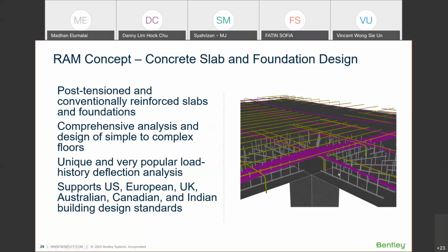So here you can see all this white color vertical reinforcement. These are shear studs, and there are manufacturers of shear studs in many countries. These are useful to withstand this punching shear. Sometimes you may need them together with the column drops. Sometimes you can avoid putting the column drops, and with the help of the shear studs itself, you can withstand the punching shear check. This program also is very popular in calculating the long-term deflections, considering the creep and shrinkage.